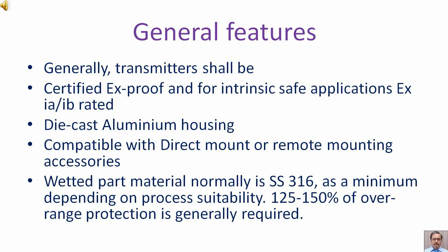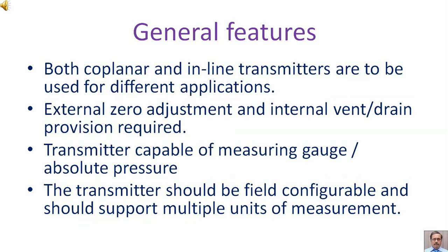Wetted part material normally is SS316 as a minimum depending on the process suitability. 125 to 150% of overrange protection is generally required. Both coplanar and inline transmitters are to be used for different applications. External zero adjustment and internal vent/drain provision required.